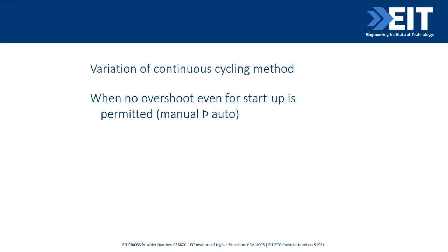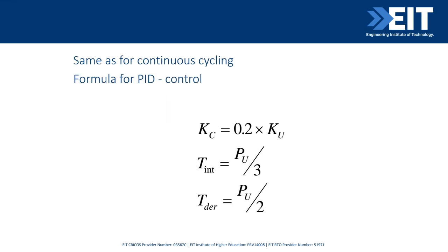For example, here you'll see if you want no overshoot at startup, you want your process variable just to creep up slowly. Can you see here you've got a really, really low value of gain. The gain here is extremely low, and it's because you want to try and be as conservative as possible. And obviously your integral and your derivative control, you want to make sure that you are as conservative as possible so that your process variable just creeps up.